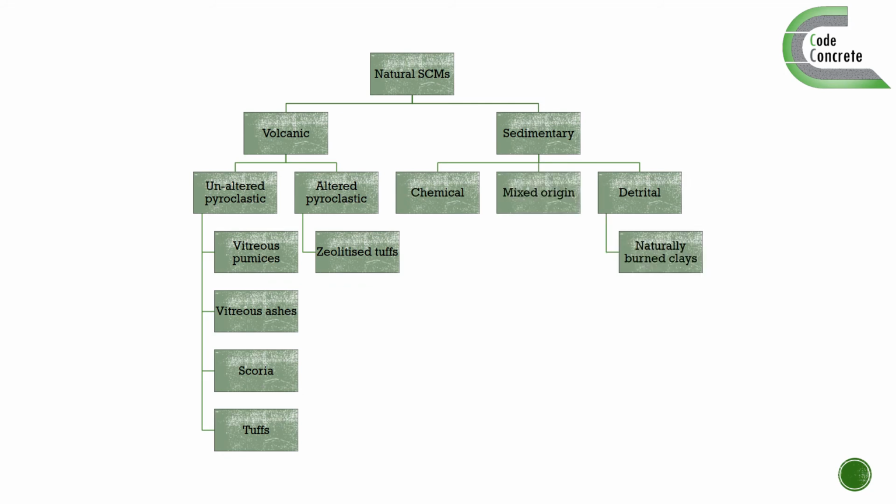Detrital sediments, such as naturally burned clays, have a low pozzolanic activity despite their high silicate content. However, grinding such sediments to ultra-fine particles and applying thermal treatment can trigger their pozzolanic activity.